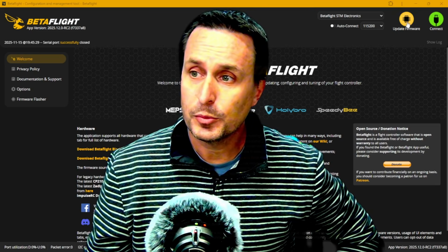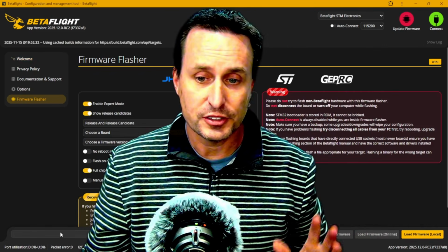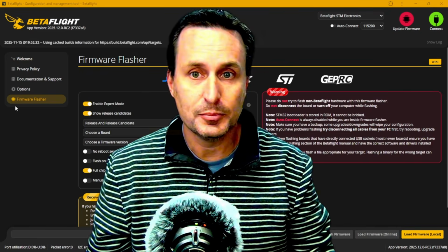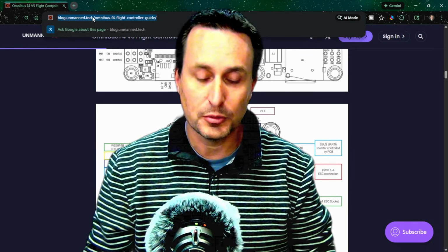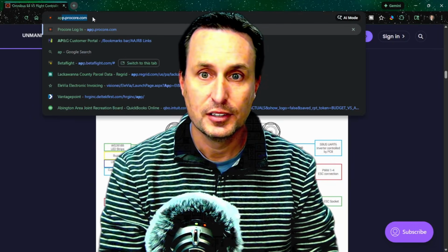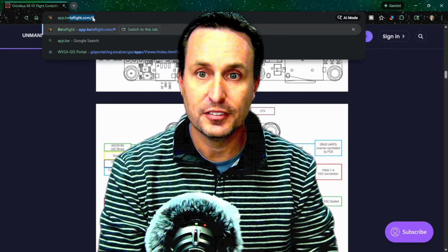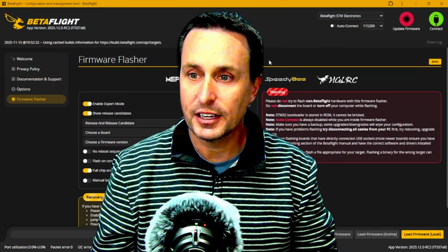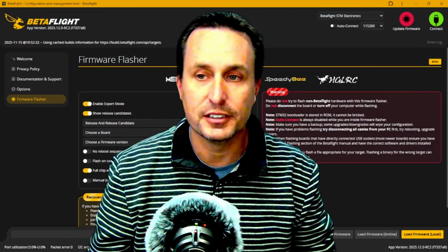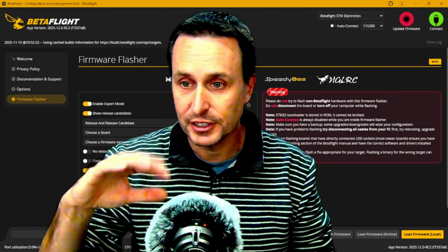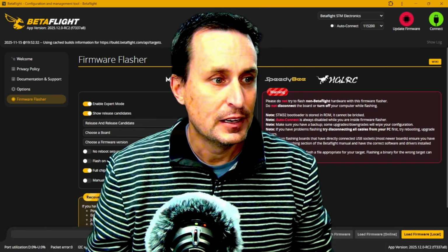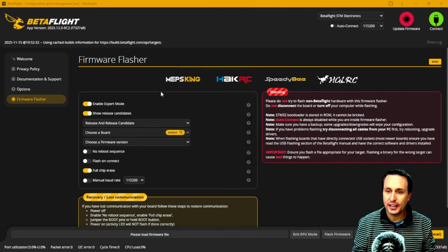Now, to flash this up, we're going to go to the firmware update. First, if you're not familiar at all, we go to apps.betaflight.com in your Windows Chrome browser. That will take you to this website. You can hit the little button up there in the address window and then just download it and have a local install of it, like a cached install. Nevertheless, using the BetaFlight app, we're going to go ahead and detect the board.